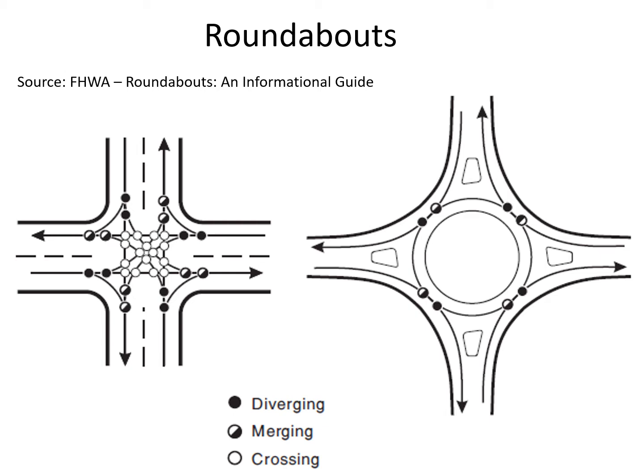A very common approach for solving the left turn issue is using roundabouts. This is showing a roundabout compared to a typical four-leg intersection: you eliminate all of those, in particular, very dangerous crossing conflicts, and you simplify that intersection, removing those left turns. Everybody turns right around the roundabout and then exits at the appropriate leg. So roundabouts are a great solution for removing those left turning movements.